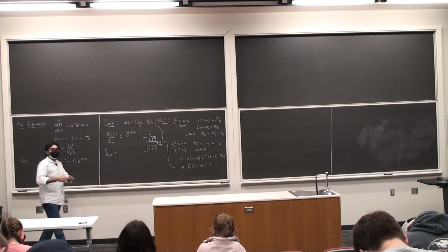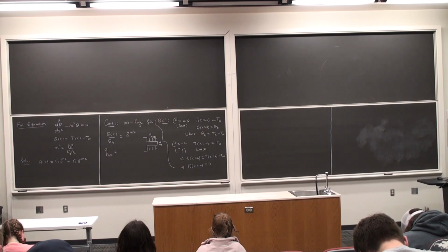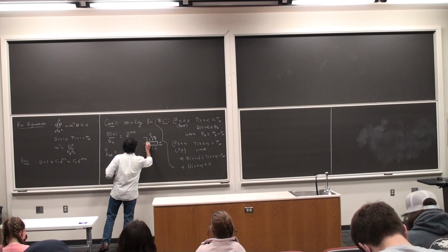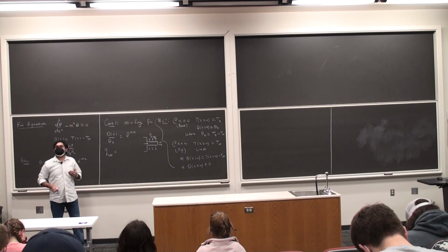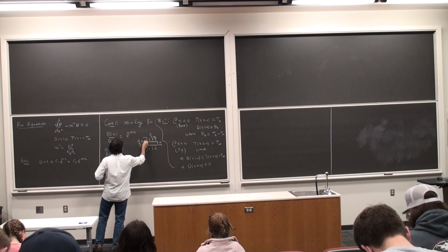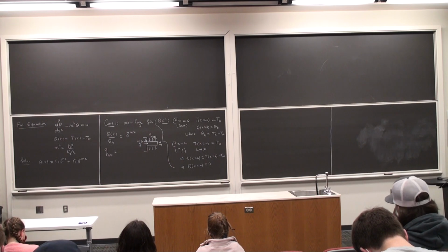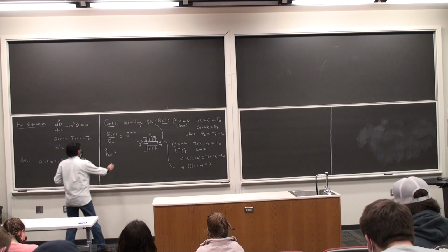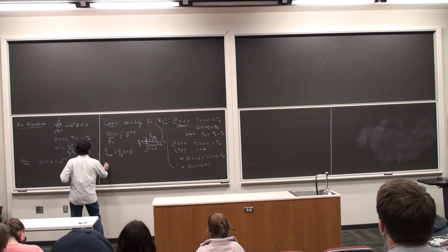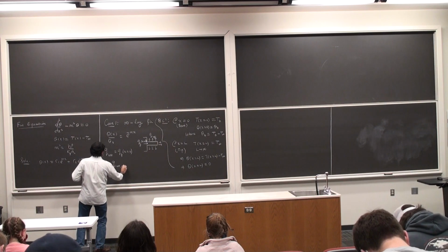So this is Q loss, which is the heat loss rate from the fin onto the ambient, which is the purpose of a cooling fin. And this is equal to the conductive heat transfer rate at the base of the fin. Okay, so this is equal to Q fin at x equal to 0. This is true for all types of fins, not particularly an infinitely long fin. And for an infinitely long fin,